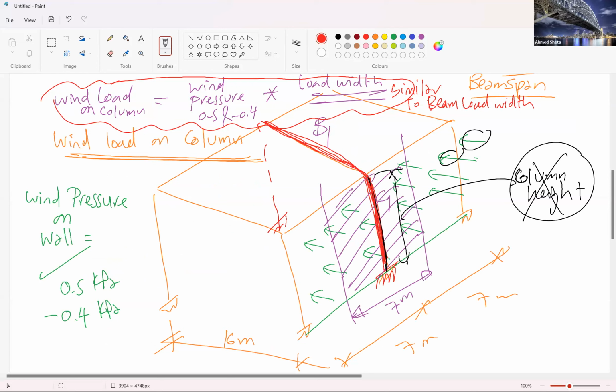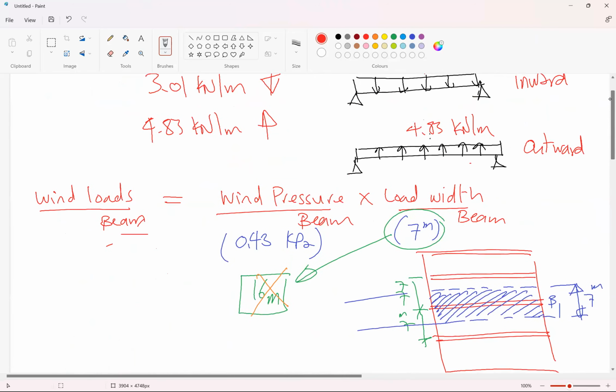In steps, you have to calculate the surface wind pressure and alternate wind pressure on the roof, and the surface wind pressure and alternate wind pressure on the wall. The load on B1 will come from the wind pressure on the roof, related to the beam, and the wall related to the column.